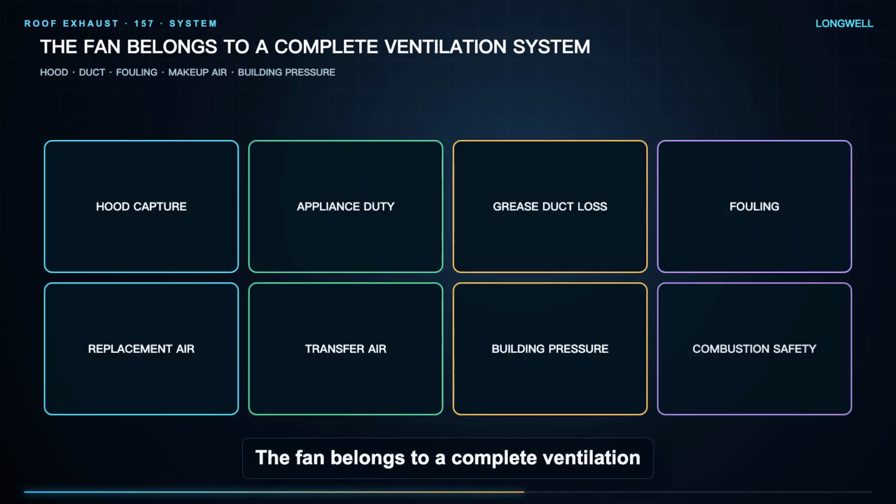The fan belongs to a complete ventilation system. Hood capture, appliance duty, grease duct and fouling loss, replacement air, transfer air, building pressure, and combustion appliances all affect performance. Roof fan CFM alone cannot prove capture and containment.